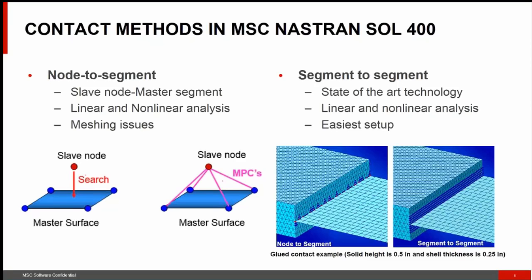It doesn't rigidize it. And there is another method available, and the second method is known as segment-to-segment contact. In this case, multiple auxiliary contact detection points are placed on an edge or a face of a body, and contact technically occurs between these points or segments.